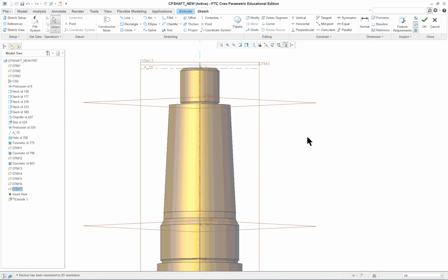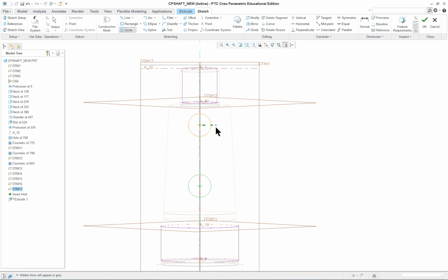A little bit on it, and you can change this if you want. We can sketch it here, but you can see that it's not 90 degrees perpendicular to the center line, to the datum plane here. It's actually parallel to, or we're looking normal to that edge here of the taper. So we do have a reference down the middle. So again, this is simply the same thing. There is one little difference in this one. So put in a couple of equal circles. Should have done this first, hidden line.